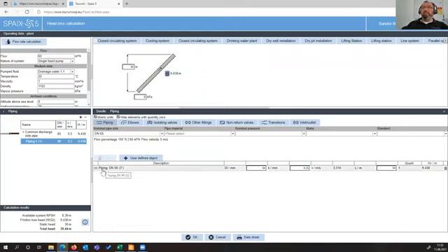You can see here the 3-inch piping with the inner diameter of 80 millimeters. This 80 millimeters causes an additional head or friction loss of 9.438 meters.